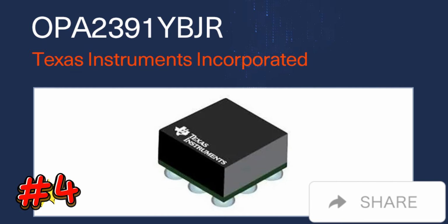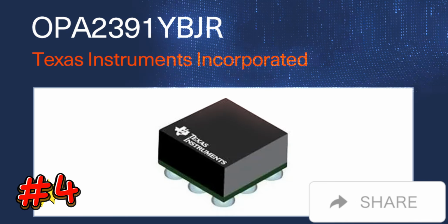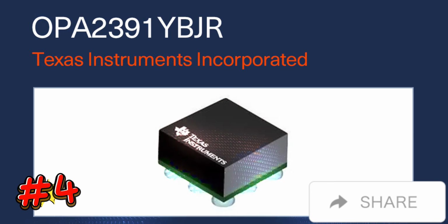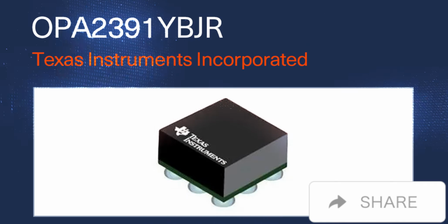Specifically, the OPA2391 utilizes proprietary eTrim operational amplifier technology, enabling a unique combination of ultra-low offset and low input offset drift without input switching or auto-zero techniques. This Texas Instruments technology tolerates high output capacitance to alleviate stability problems that are exceedingly common in low power amplifiers.